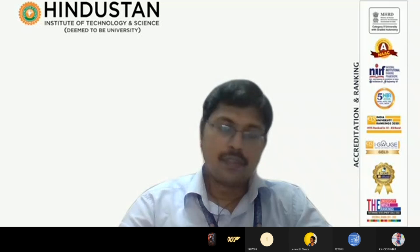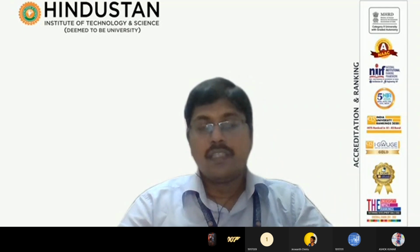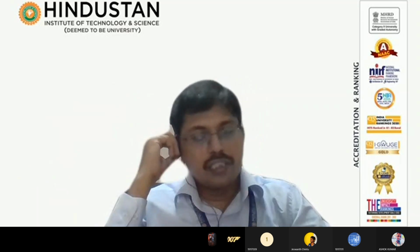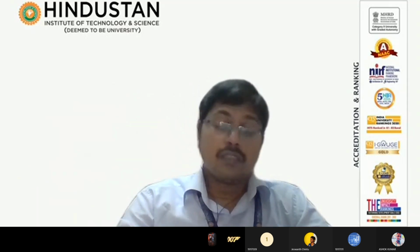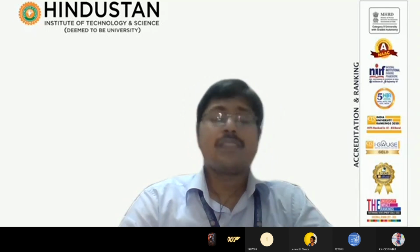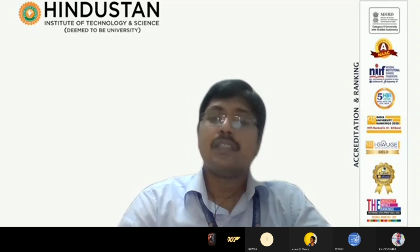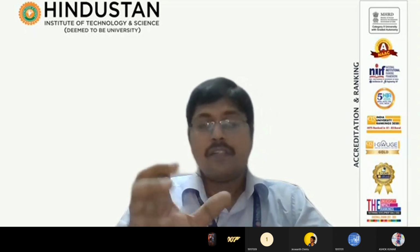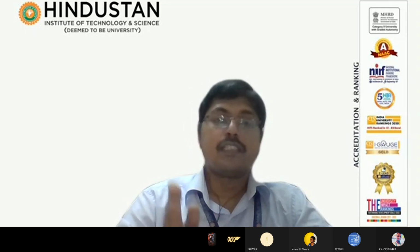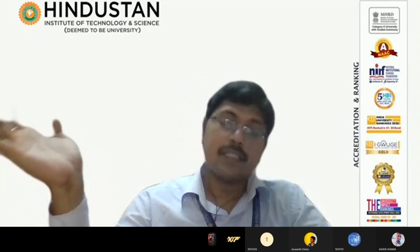The last unit we discussed time response analysis. So we know the importance of the time response. What are the inputs and what will be the outputs? Any type of response, the input will be in terms of its domain, and the time response we got it through time. That means in terms of time domain specifications. Especially in the second order time response, we analyzed different types of time specifications, starting from delay time, rise time, peak time, maximum overshoot, and settling time.